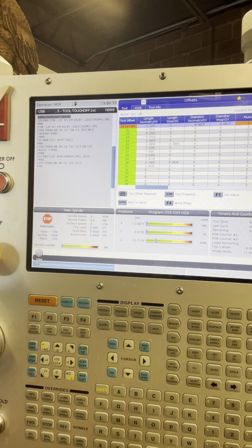that nozzle. Okay. So if I touch off 18 tools, if you don't do that, it sprays it at the bearings on the spindle. It's way up the spindle. It's a pain in the butt. So instead of doing 18 times of waiting for the tool to start and then bringing it down and setting your number, we did that. And again, it's one of those that we'll adjust once in a while, but it's rare.